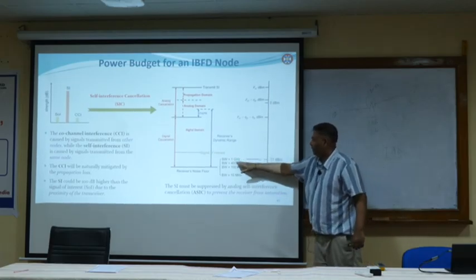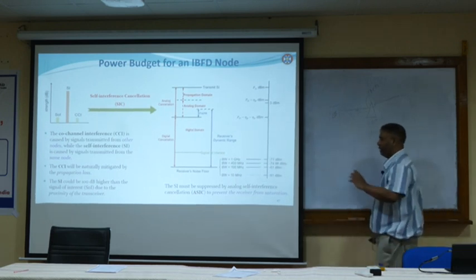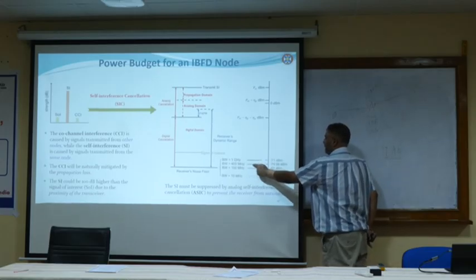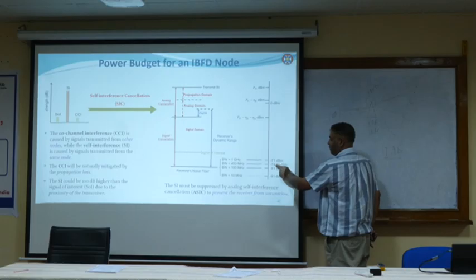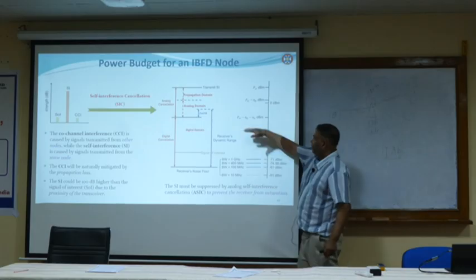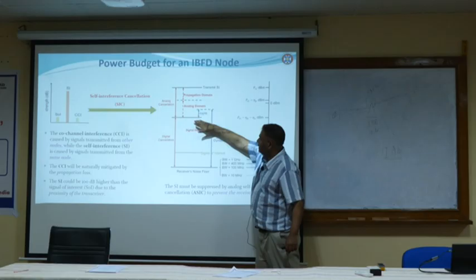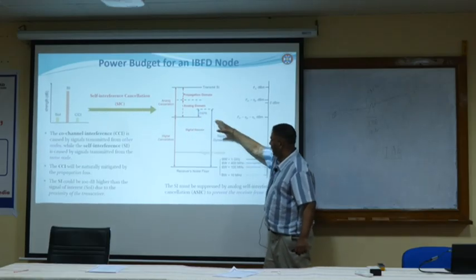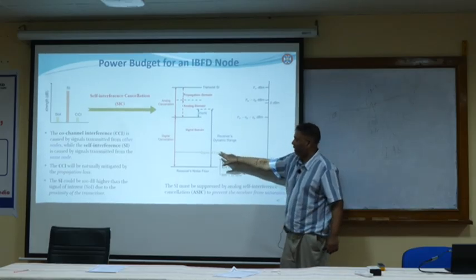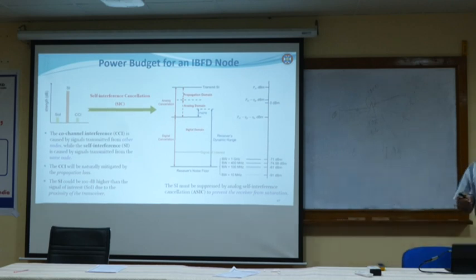If you increase the bandwidth to a 400 megahertz channel, as 5G millimeter wave frequency can have, your noise floor is -75 dBm. So if you do propagation and analog domain cancellation, you are here. Then the remainder you cancel in the digital domain to bring it here, and then you will be able to detect the signal of interest. That explains the power budget.